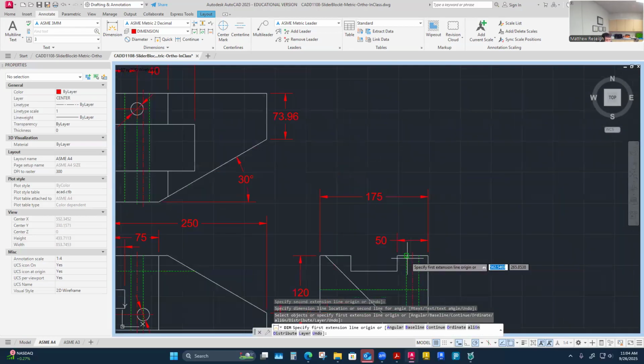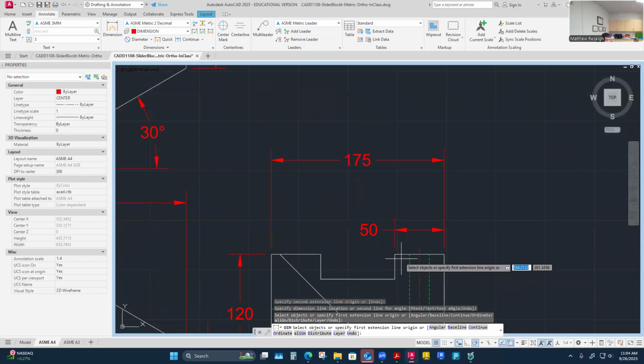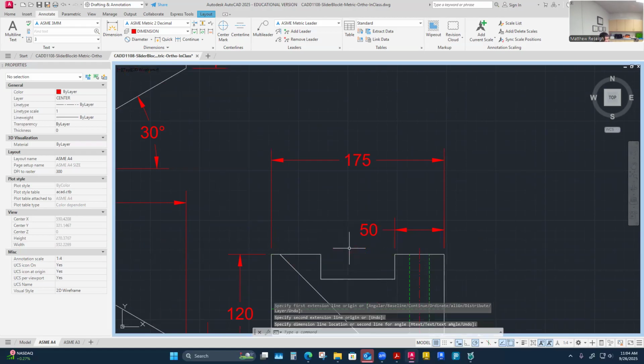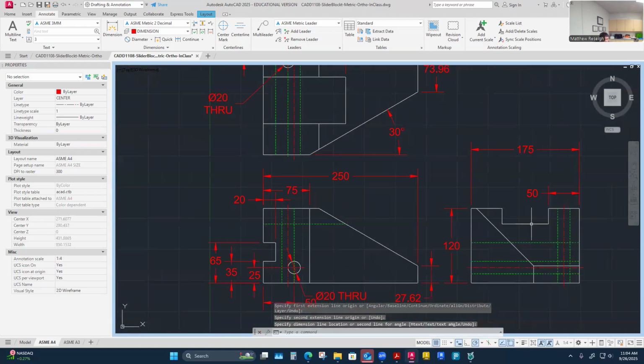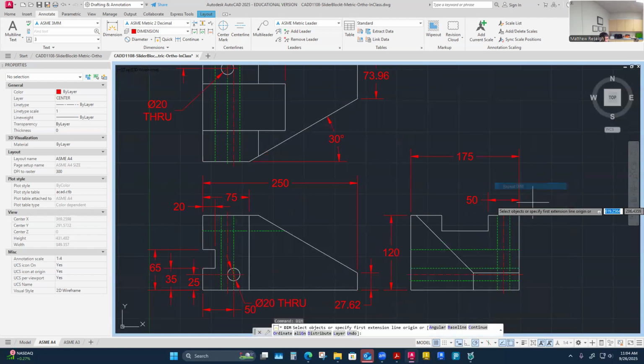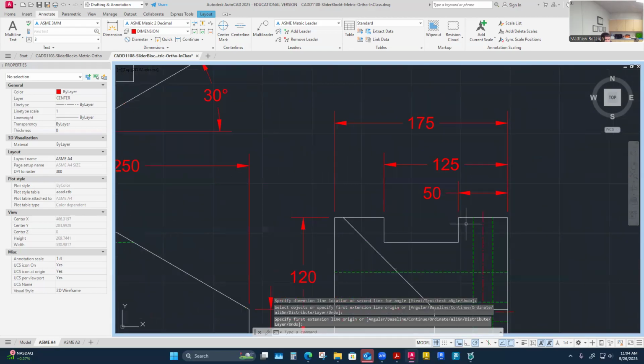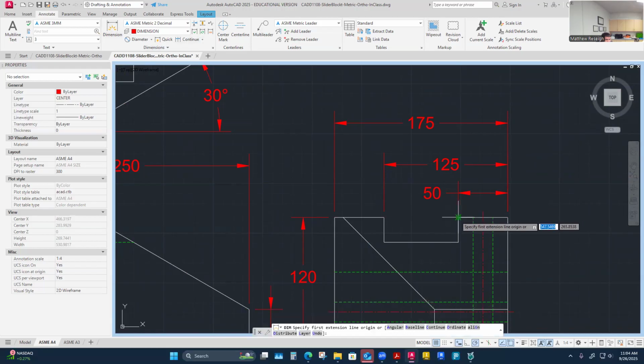The argument could be that your front view should definitely be a datum, and that's a good point. This would be stacking dimensions, right? If I kept doing this as chain dimensioning, I get the same problem with this notch as I would here. So I'm probably going to pull this from point to point from the same position here. There to there is the better dimension. If I want to know the distance across the gap, this one is handy. I think this is a good to know.